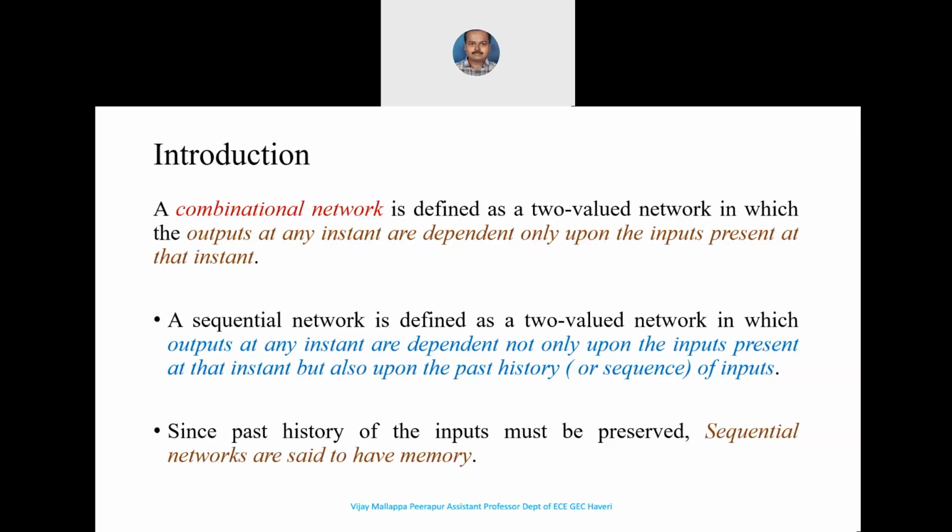In the sense, when we discussed in module 1, briefly I gave an understanding on what are combinational circuits and sequential circuits, right? It means that when I say sequential circuit, it consists of a combinational circuit to which memory elements are connected to form a feedback path. Since we have a feedback, it is dependent on the past history of inputs there, right?